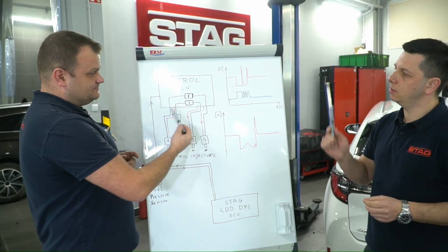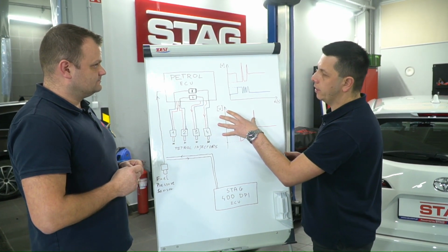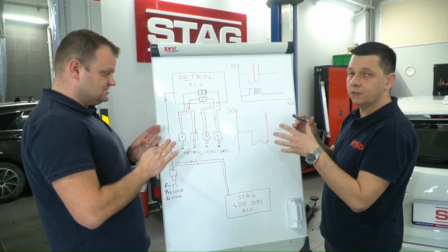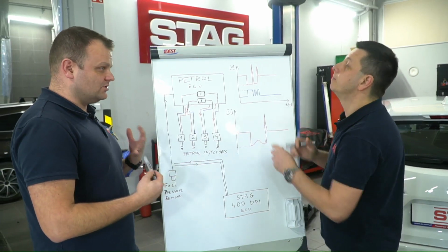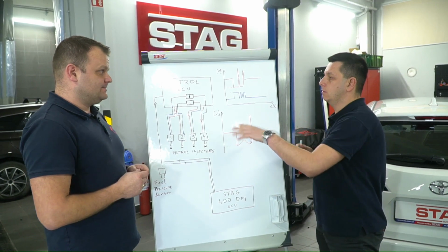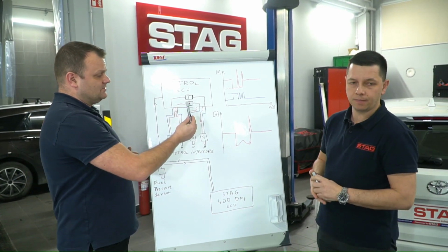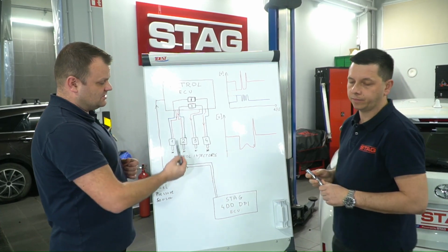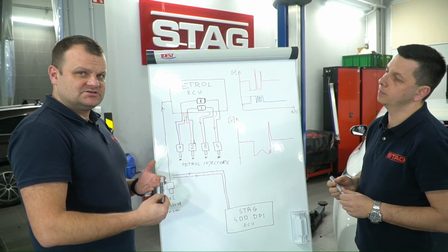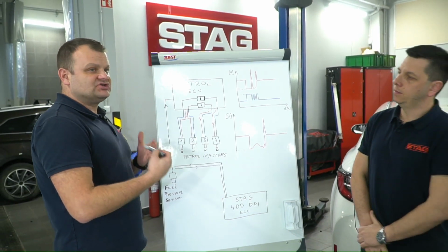One very important thing is that we are showing you the solution for 4 cylinders. In 6 and 8 cylinders the most common solution will be a little bit different when we are talking about the pairs. Because these inverters are supplying the injectors working in pairs, we are meeting some strange signals.